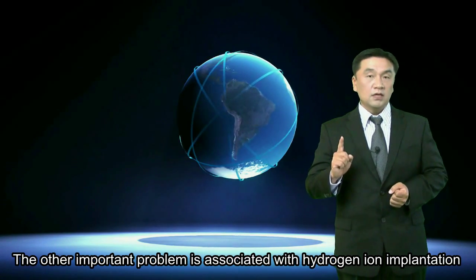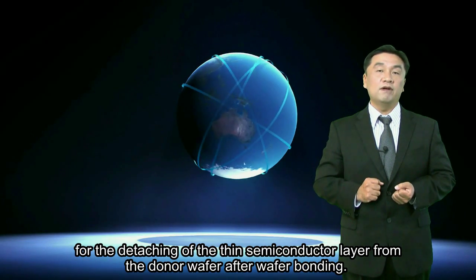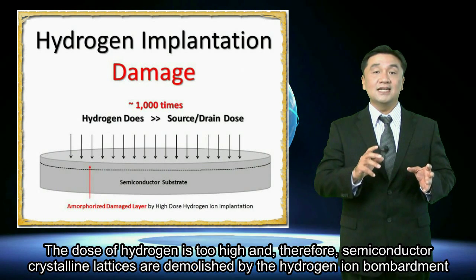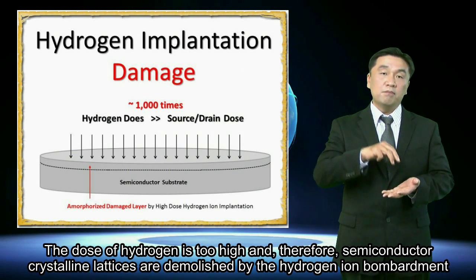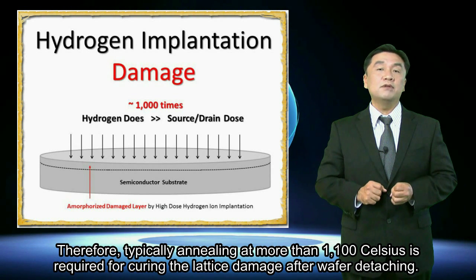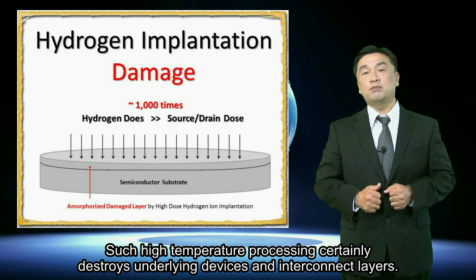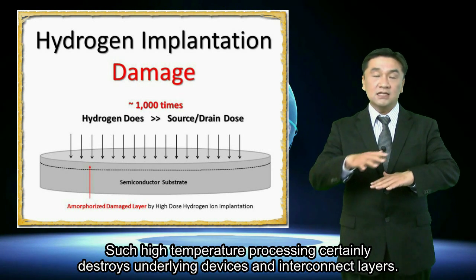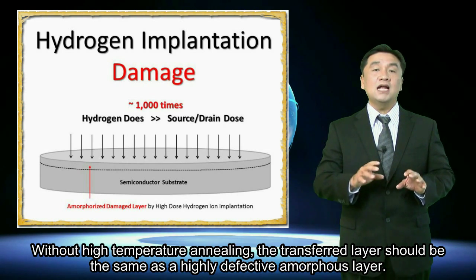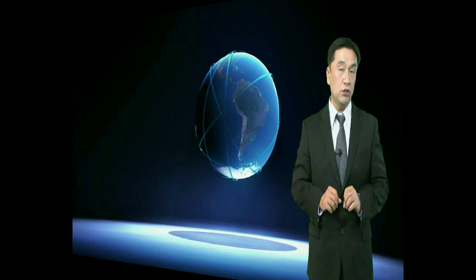The other important problem is associated with hydrogen ion implantation for the detaching of the thin semiconductor layer from the donor wafer after wafer bonding. The dose of hydrogen is too high, and therefore semiconductor crystalline lattices are demolished by the hydrogen ion bombardment during the implantation. Therefore, annealing at more than 1100 Celsius is typically required to cure the lattice damage after wafer detaching. Such high temperature processing certainly destroys underlying devices and interconnect layers. Without high temperature annealing, the transferred layer would be the same as a highly defective amorphous layer. It seems that there's no way to cure lattice damage at low temperatures.